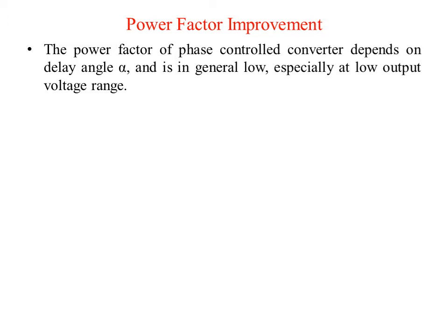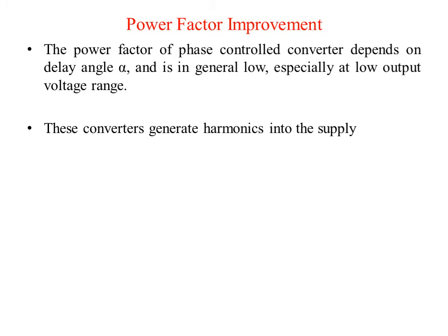So it is necessary in these phase control converters to improve the power factor. The power factor of phase control converters depends on delay angle alpha, and it's generally low, especially at low output voltage range. This converter generates harmonics into the supply.